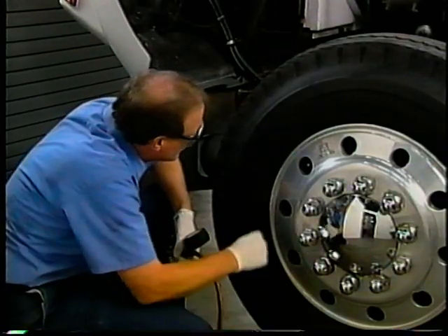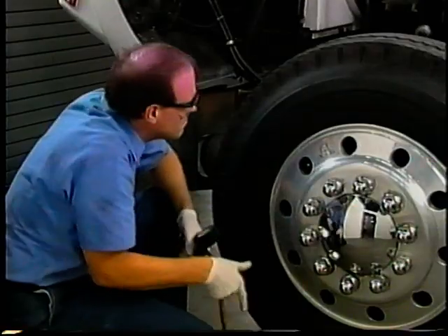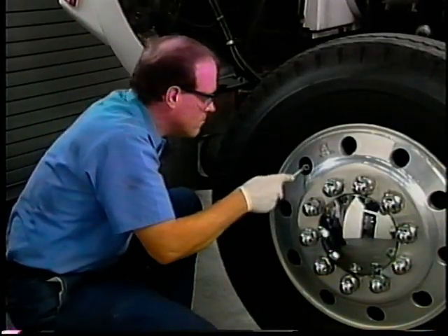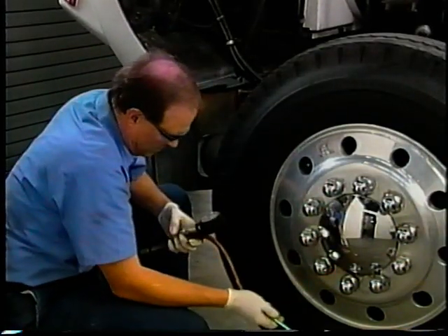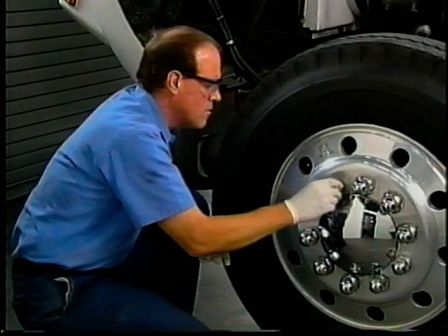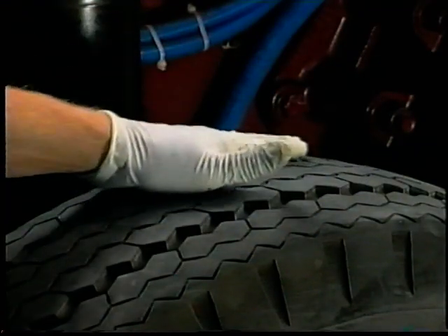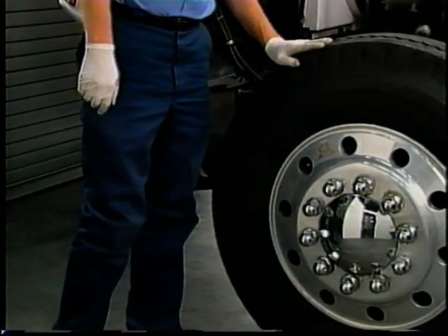The diagnosis of handling concerns related to vehicle alignment starts with the basics. Always check the tire pressures and wheel lug nut torque before road testing the vehicle. Look for loose lug nuts or rust around the lug nuts. Low tire inflation will cause problems with hard steering effort, tire wear, and can cause tire overheating and possible tread separation.